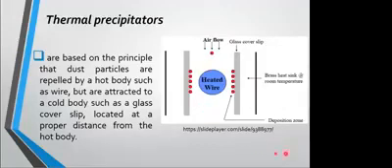So the process is, as the air is slowly drawn into the chamber, the airflow containing the elements, the pollutants or air components, then the particles in the air are deposited on the collecting surface in a thin ribbon. The modification of this method has been developed so that the particles may be collected directly for electron microscope examination. So that's why it attracts the particles to the cover slip, so you can look at it directly under the microscope to see whether depositions are present.